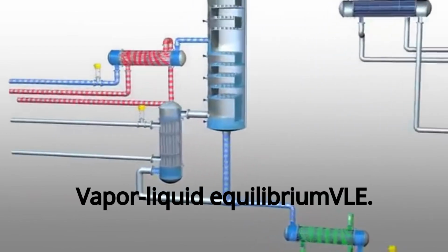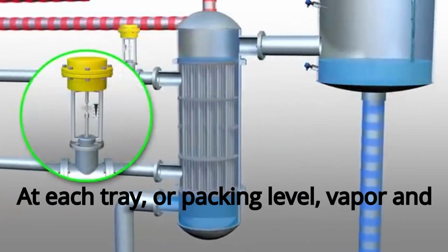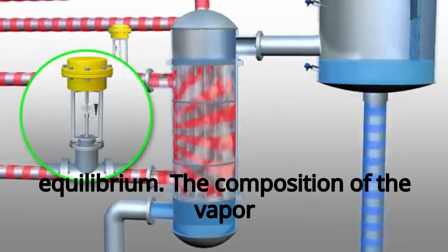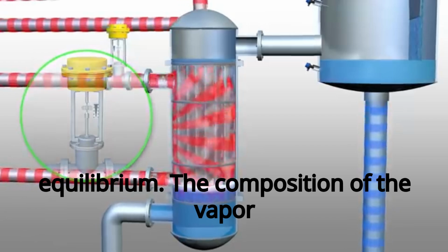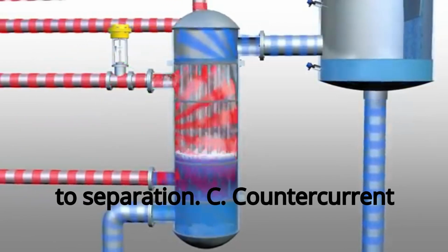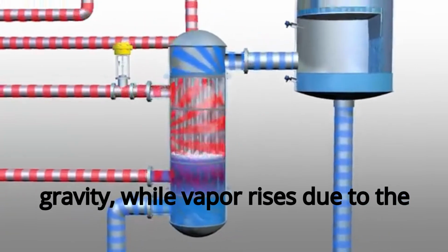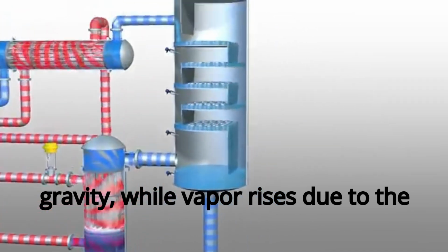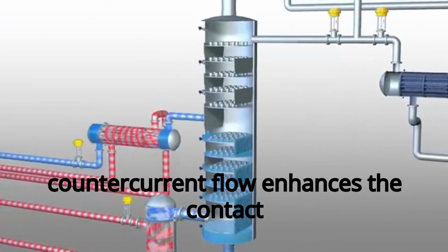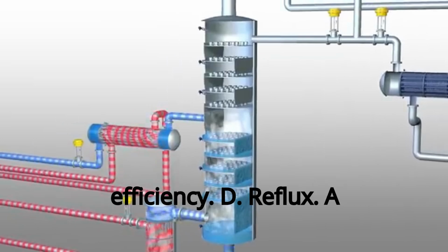B. Vapor-liquid equilibrium, VLE. At each tray or packing level, vapor and liquid phases achieve partial equilibrium. The composition of the vapor and liquid changes progressively, leading to separation. C. Countercurrent flow. Liquid flows downward due to gravity, while vapor rises due to the heat provided by the reboiler. This countercurrent flow enhances the contact between phases, improving separation efficiency.